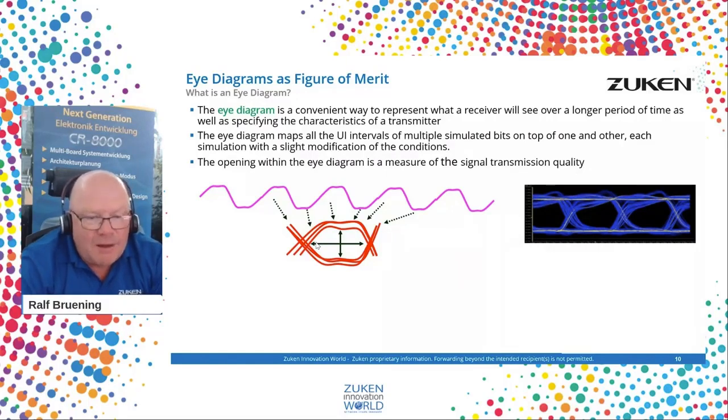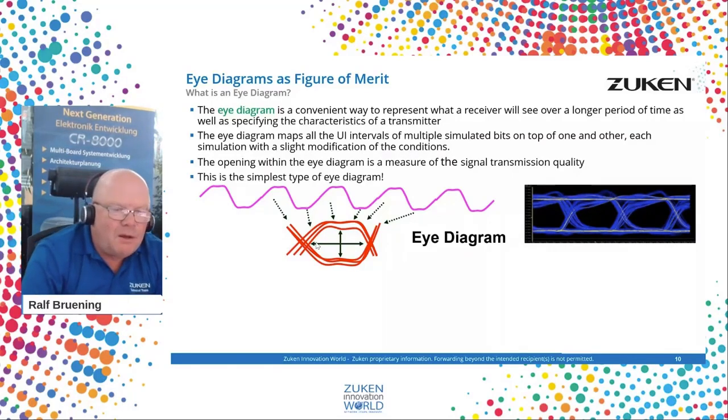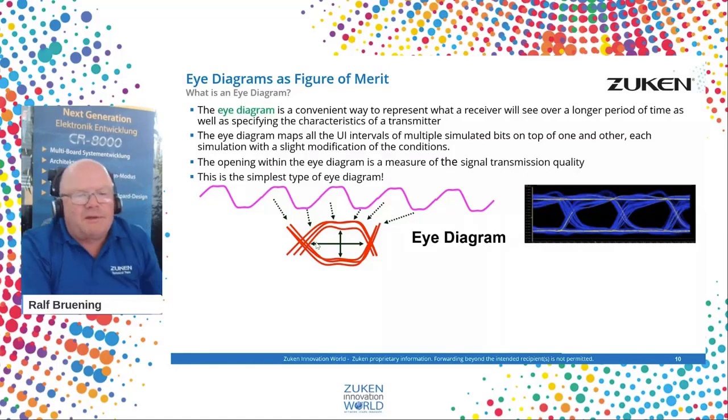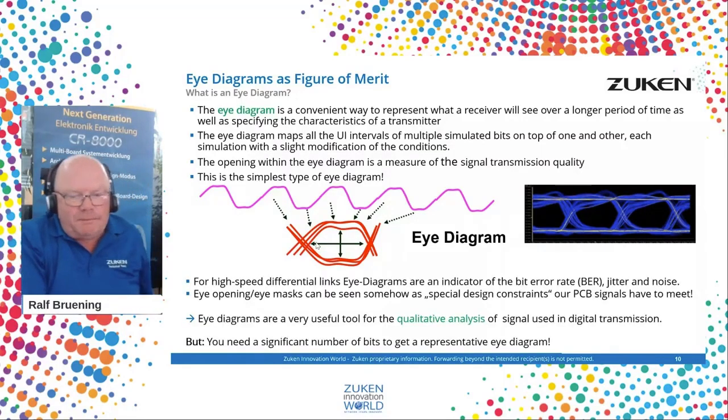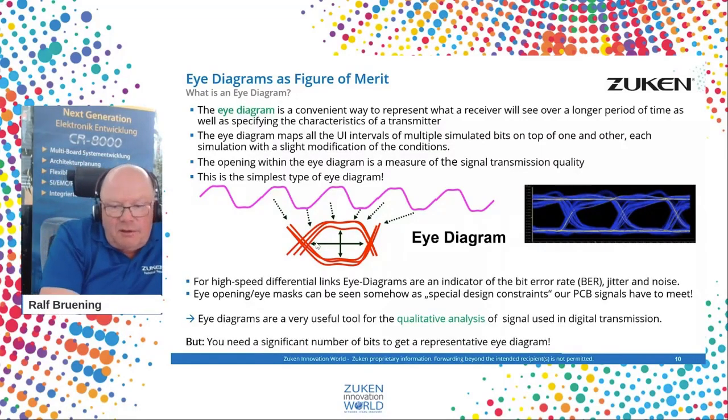the more you end up with a closed eye. And you have requirements on the eye openings from the IC vendors. They define that the eye has to have a width of a factor X and a height, or amplitude, of a factor Y. Otherwise, it is not guaranteed that the SerDes channel is operating properly. So that's the basics behind an eye diagram, and that's a typical new kind of constraint we have if we talk about constraining and implementing SerDes links.